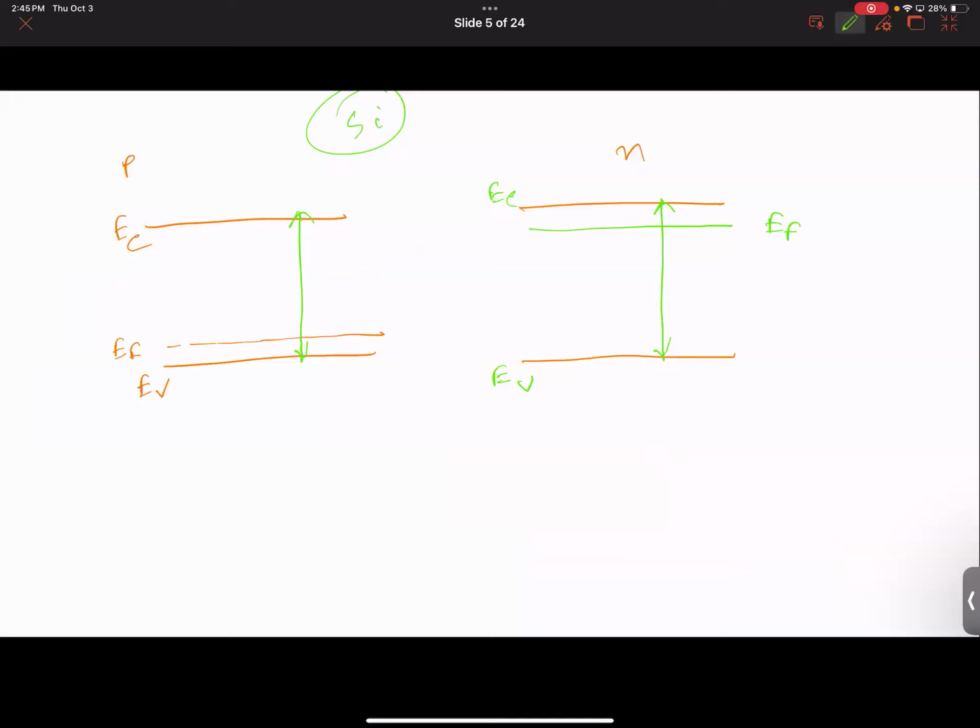Oh, that's what changed. And just by changing this, from all silicon to multiple types of materials, you can have more exotic devices. More about that later. But as of now, it's all silicon, so this band gap should be exactly the same. All right, now, when you bring this together, the first thing that you should care about is flattening the Fermi level. The Fermi level should be flat at thermal equilibrium, obviously. That means you haven't applied any external voltage, remember that. So Fermi level should be flat across the stack, N and P.